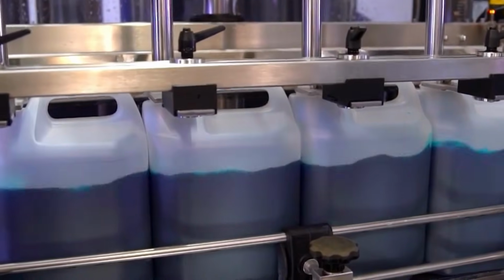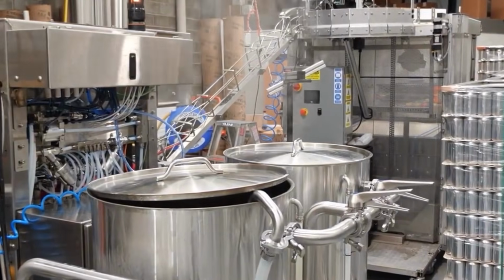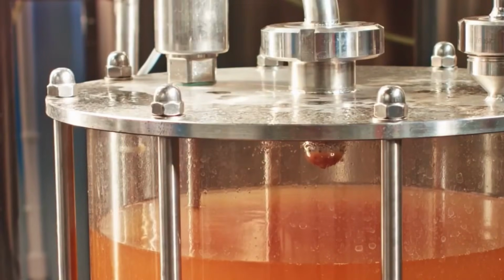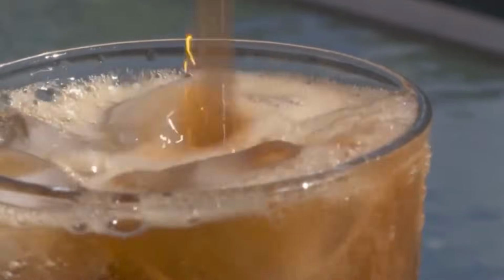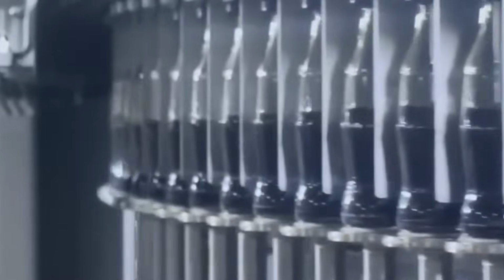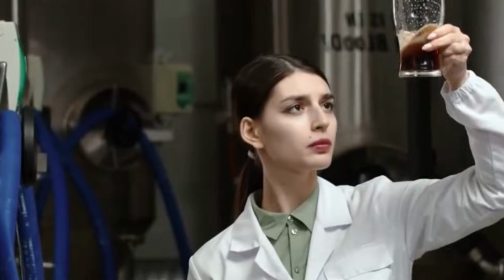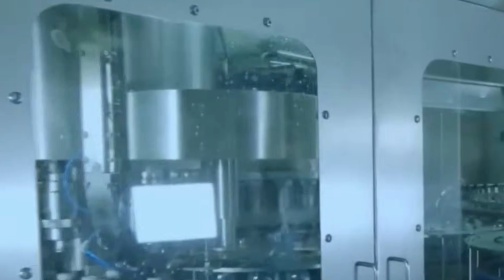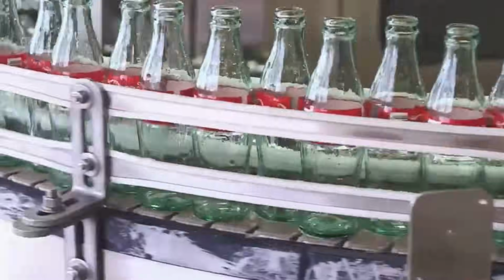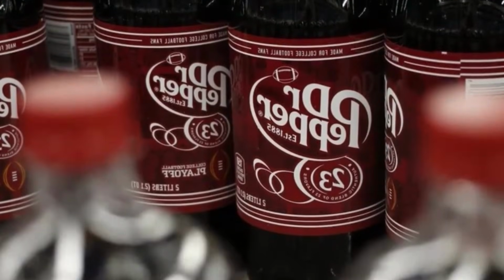Concurrently, concentrated syrup production begins. This involves a precise blend of liquid sweeteners, flavor concentrates, acidulants, and coloring agents. High fructose corn syrup or liquid sugar arrives in tanker trucks and is pumped directly into insulated storage silos. From there, metering pumps draw exact amounts of sweetener into stainless steel mixing vessels. Each vessel is jacketed for temperature control and fitted with high-speed impellers. Flavor compounds are stored in temperature-regulated vats and dispensed in minute quantities using servo-controlled dosing systems.